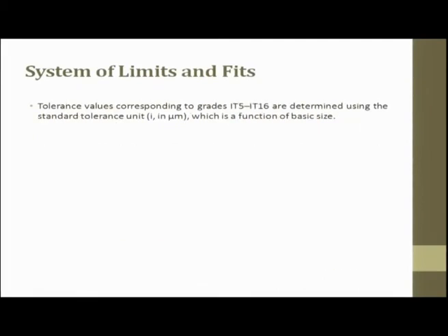The tolerance values corresponding to the grades IT5 to IT16 are determined using a standard tolerance unit, i, in micrometers, which is a function of the basic size. This is an empirical formula: i = 0.45 times the cube root of D plus 0.001 D, in microns, where D is the diameter of the part in millimeters.